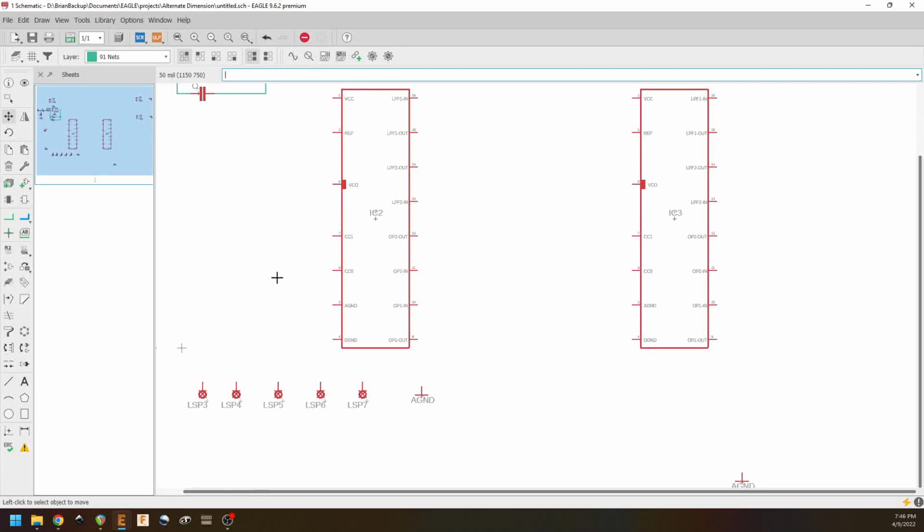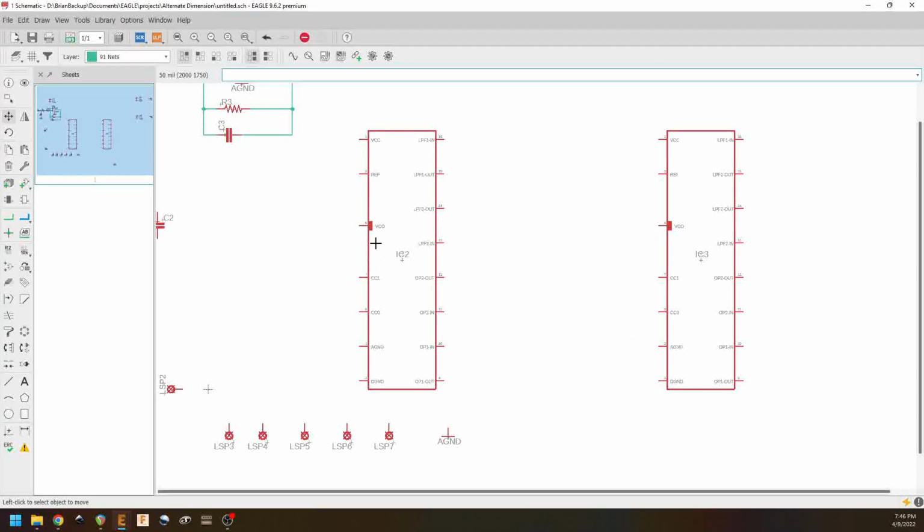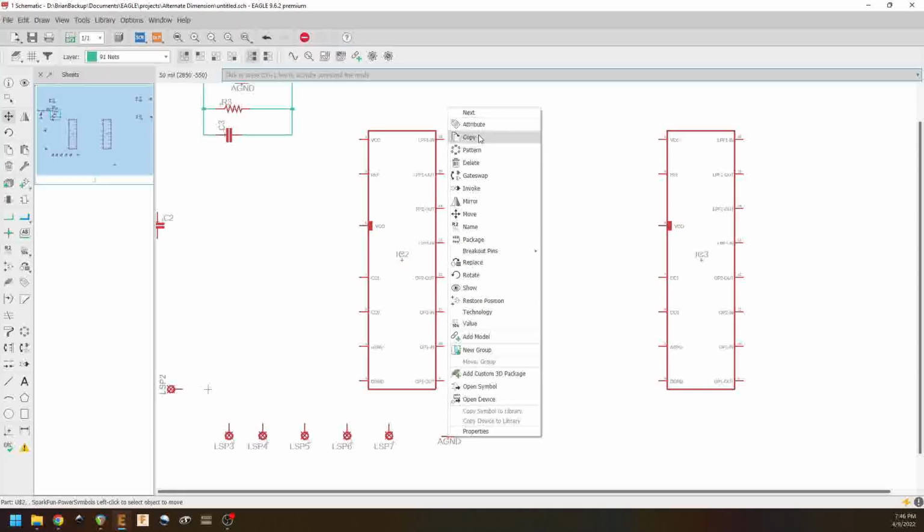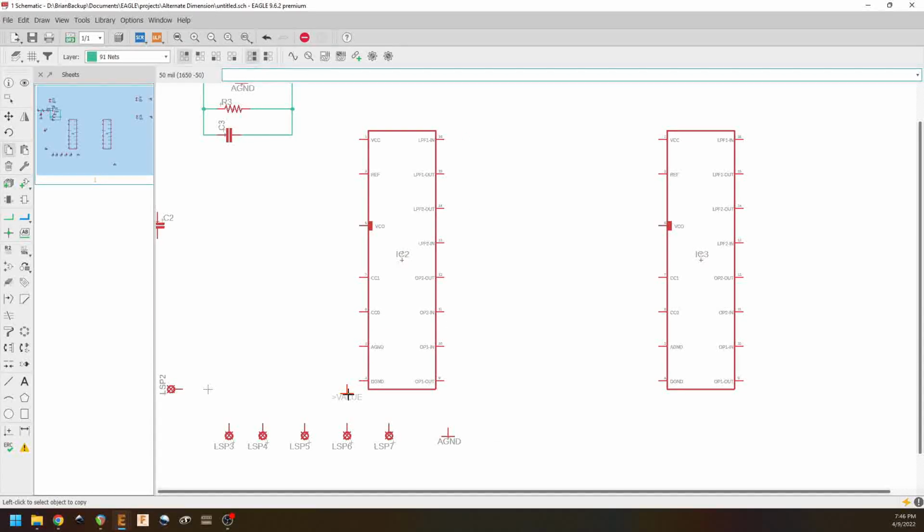Now you'll notice that the pins along this side of this particular package don't correspond to the physical pins. We have pin 1, 2, 6, 7, 8, 3, and 4. That's done just because it's convenient for these ground pins here. So what I'm going to do is grab myself another ground symbol. Just put him here. Tie our grounds in.